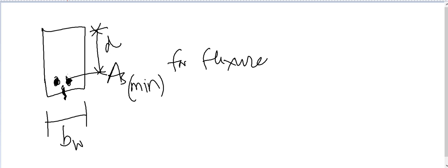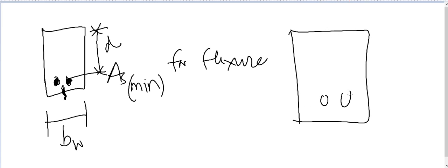It is a control factor in slab, because in slab we need so little reinforcement that sometimes my required reinforcement is less than the temperature. We cannot provide that. So if I give you the summary, this reinforcement must be greater than temperature for slab. This reinforcement must be greater than the minimum for concrete cracking.